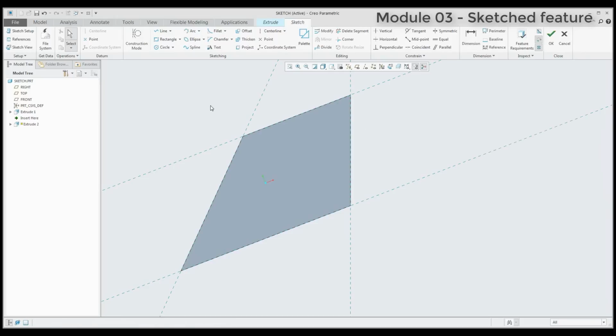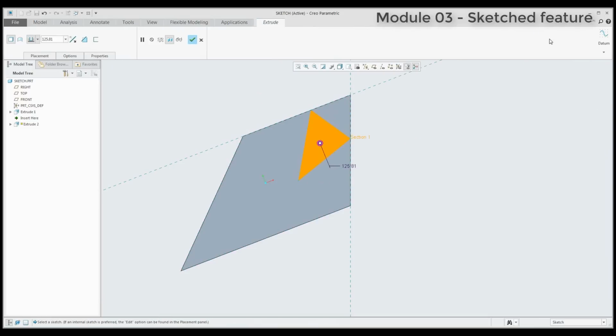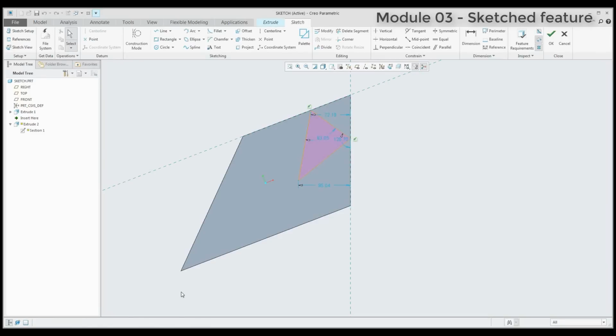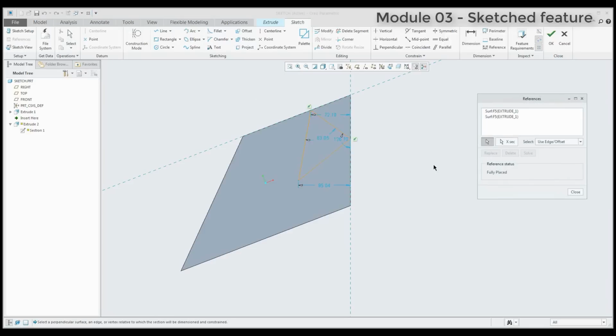And if you use these references in your sketch, the system will remember. For example, I will create a really easy rectangle, I will connect only 2 edges. Yeah, you can see here that I will attach my sketch directly to 2 references. And the system automatically will remove unused references. So if I confirm this sketch, and then I go back to the sketch, so you can see here Placement and Edit, the system removed the references. So that's perfect. You can add as many references as you need and the system will use only what you select.